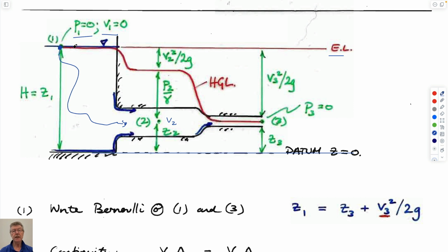So right at this point here, this is the elevation head, Z1. The pressure head is an infinitesimally thin line, and the velocity head, V squared over 2g, is an infinitesimally thin line here. They're all converged. As you come here, they diverge. The velocity will widen out, finite, and we'll lose elevation at the expense of both pressure and velocity. As it further constricts, then